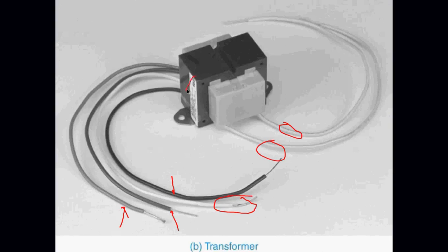And you look at the label on the transformer, and it will tell you what wire connects for what voltage. And you've got to be really careful about this. Because if you connect a 120 volt situation into a 240 volt circuit, it may not burn out the transformer. The transformer may actually stay running. But instead of having an output of 24 volts, you could have an output of 48 volts. So if you connect the wrong terminal, the transformer may not blow up, but you may melt down whatever you have connected to it.